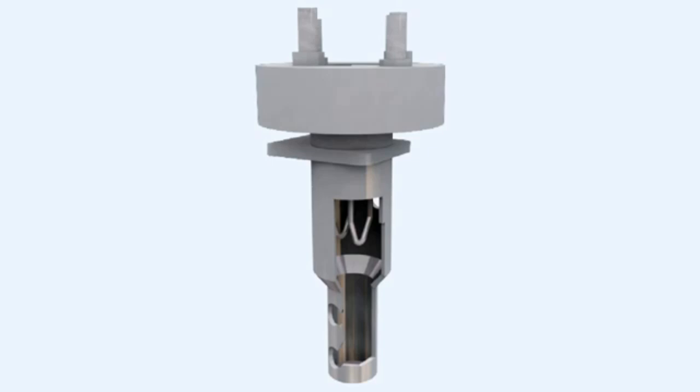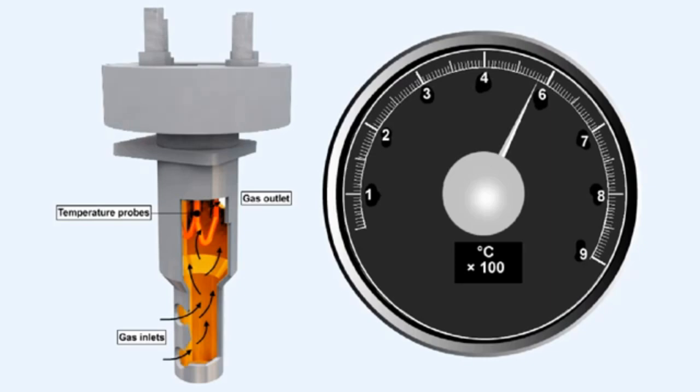The gas temperature must be monitored closely, and automatic temperature limiting equipment is fitted to most gas turbine engines operating today. To enable this monitoring to be achieved, temperature probes are inserted in the gas stream. Temperature probes are formed from the junction of two dissimilar metals, which, as we've just seen, generate a potential when the junction is heated. The potential is proportional to the temperature applied to the junction.